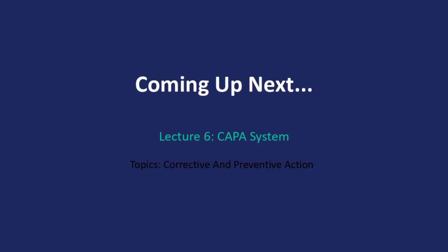In this lecture, we learned what deviations are and why they matter, how to classify deviations by severity, the difference between OOS and OOT, the deviation management process from detection to investigation to CAPA to closure. Root cause analysis tools including 5 Whys, Fishbone, and Fault Tree, common mistakes in root cause analysis, the importance of documentation and timelines, how to build a culture that supports deviation reporting, and the value of tracking deviation metrics.